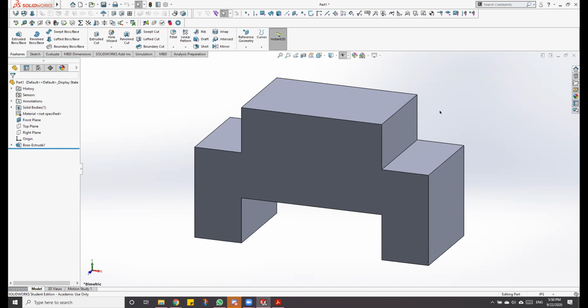I could hear it. Okay, so if it's an actual hole size, like a screw, a dowel pin, an actual fractional size, or a metric screw, something like that, do not use your extruded cut feature. You use the hole wizard, which in my case is my W shortcut.